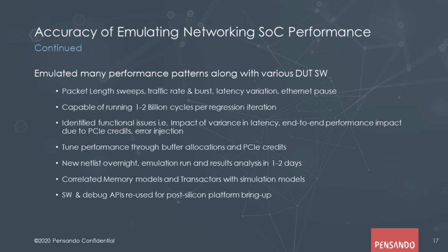We also went over lots of cases where we had to debug issues. Some are functional, some are non-functional. Overall, it worked out really well. We easily got waveforms, we debugged, and then we reran them, and the cycle becomes really faster. The synthesis flow is also automated over here. So overnight, we get a new design synthesized, and if it is not the full SoC but a sub-SoC, then it is even faster. That also helps us a lot.